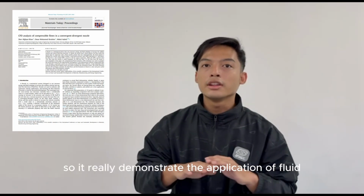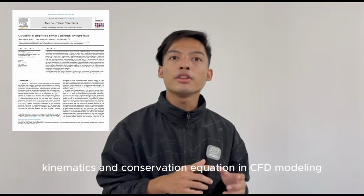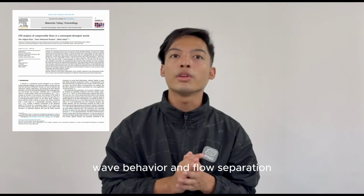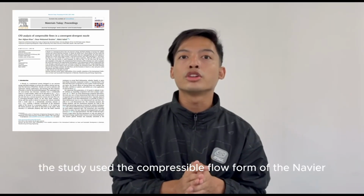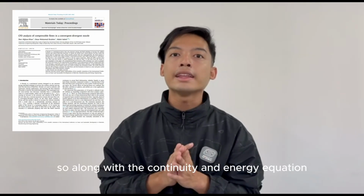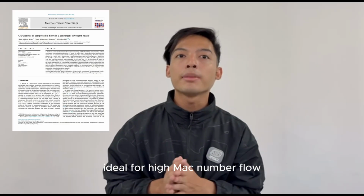It really demonstrates the application of fluid kinematics and conservation equations in CFD modeling for high-speed compressible flow. They emphasize the importance of accurately simulating shock wave behavior and flow acceleration in the supersonic regime. The study used the compressible flow form of the Navier-Stokes equation, along with the continuity and energy equations, and they employed a density-based solver ideal for high Mach number flow.